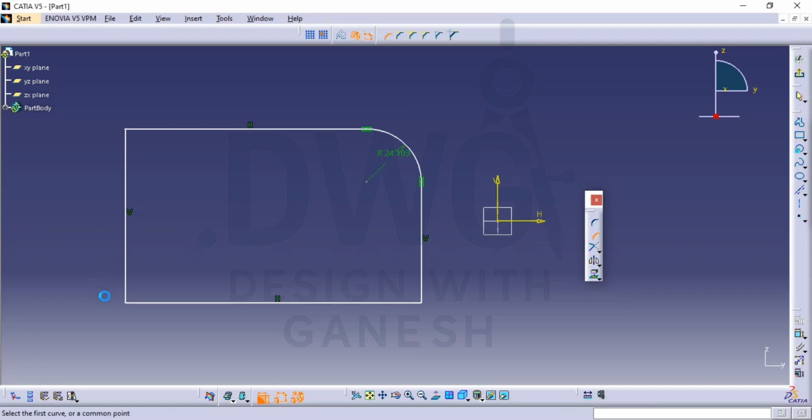And if you click on the chamfer, select the two entities, so here you can see the flat option. So this is the difference between the flat fillet and the chamfer options. For example, these are for industrial purposes. Whenever there are sharp edges, industrial parts won't maintain sharp edges. For those you can use the chamfer and fillet options.